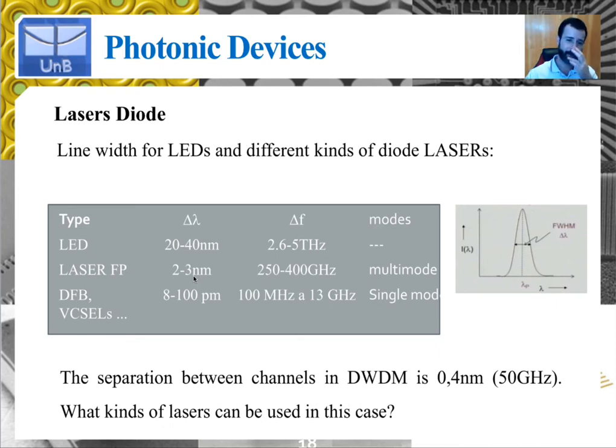And this is because, again, we're using a cavity, so the frequency response of the laser will have to take into account the transmittance of the cavity itself. And since it is a cavity, it's going to have a line width which depends on the quality factor of the cavity, right? Now, the Fabry-Perot laser usually relies on a cavity where the mirrors have a reflectance of around 30%.